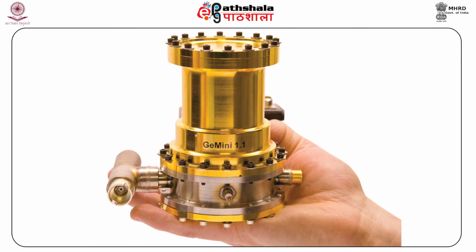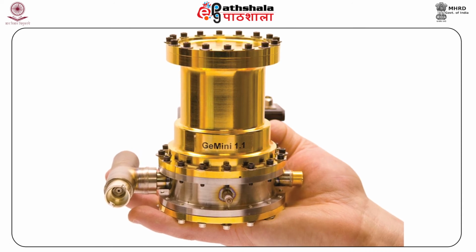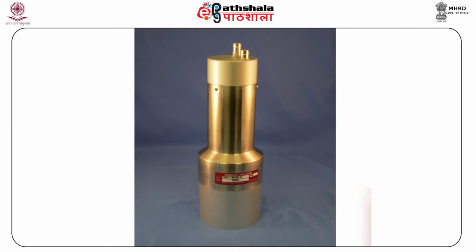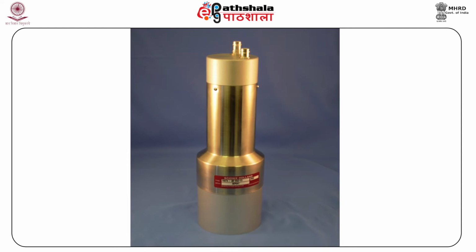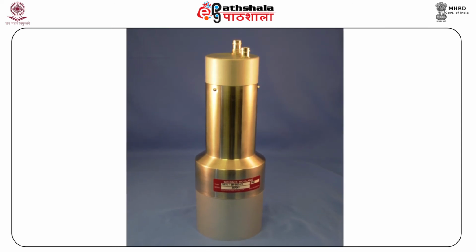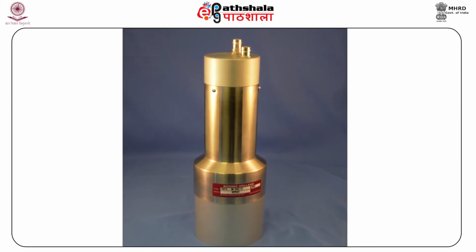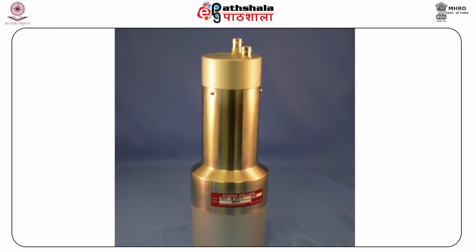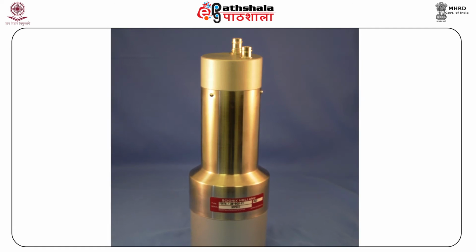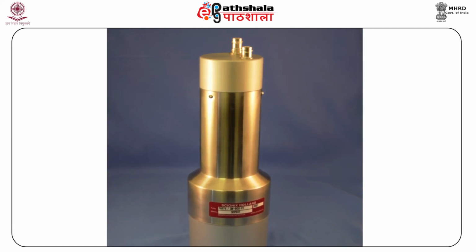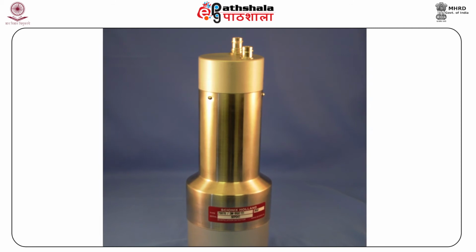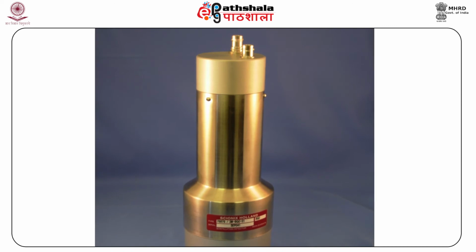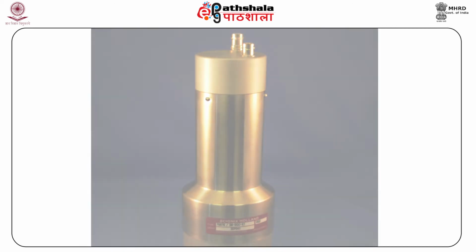Of these, the scintillation and semiconductor types are the most widely employed. The second type of detector employs a radiation sensitive crystal, most commonly thallium doped sodium iodide, that emits light when made to collide with gamma photons. All these detectors have resolution, sensitivity, and stability.